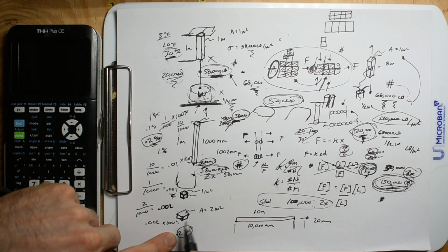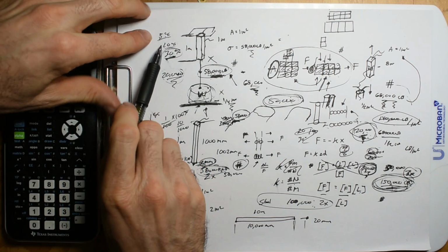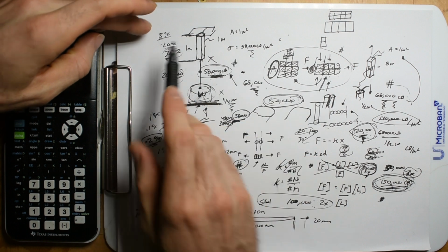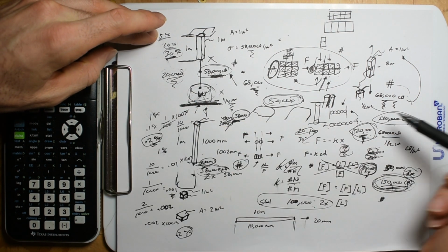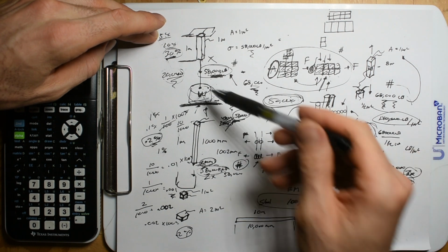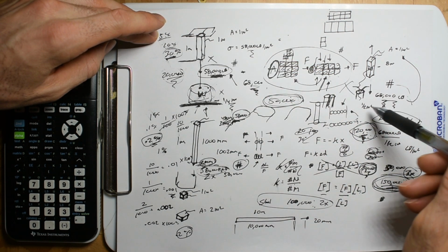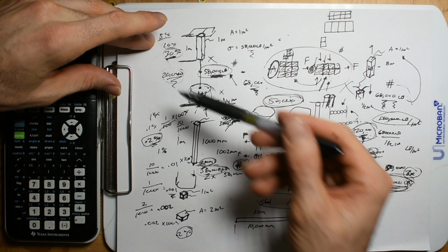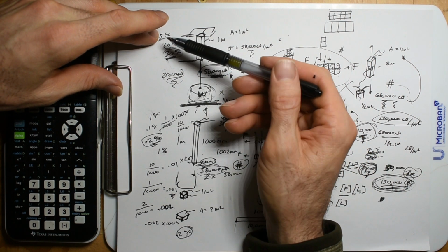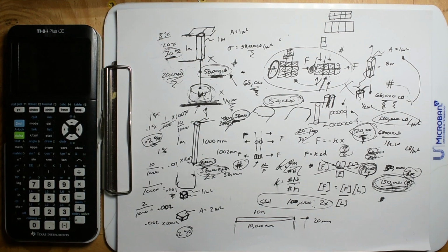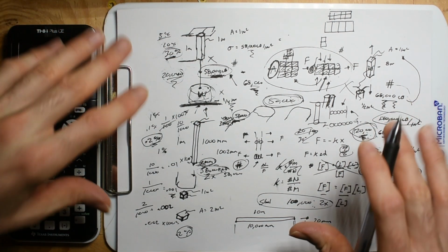So just compare 0.2% to 5%. The fact that steel could stretch visibly, noticeably 5%, still get stronger, have all its same holding capacities, might break. At some point it's just going to break, and catastrophically. But you have this window of stretch, 5, 10, up to 30% for a perfect specimen. Oh, well, I know how to bring this home now.